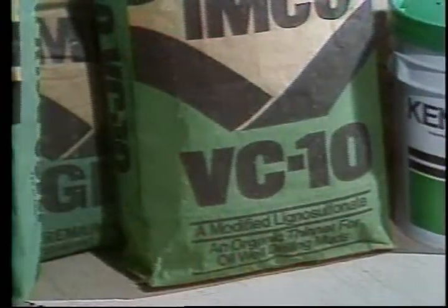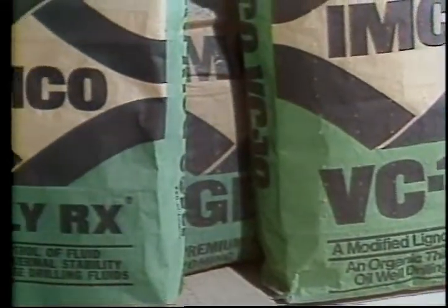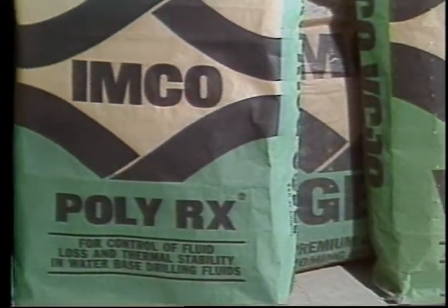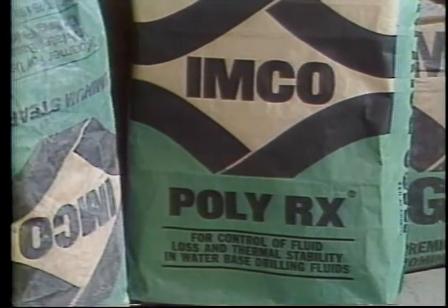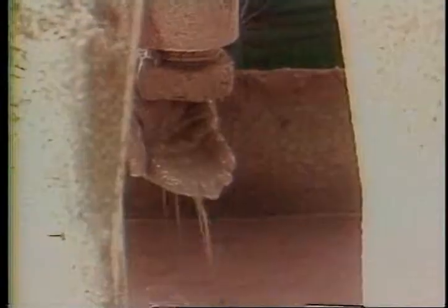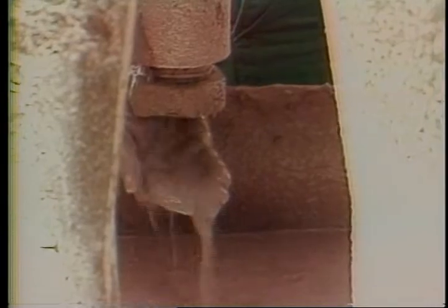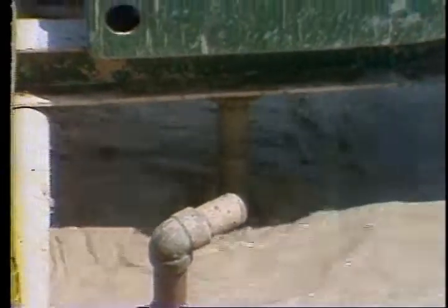There are a whole lot of additives to help improve or control the natural features of bentonite. Too bad it's not just that simple, though. Everything that the driller drills up is a contaminant to the mud system. Most of the solids that he gets into are taken out by your solids control equipment. But when the cuttings start having an effect on the chemical properties of the mud, other things have to be done.